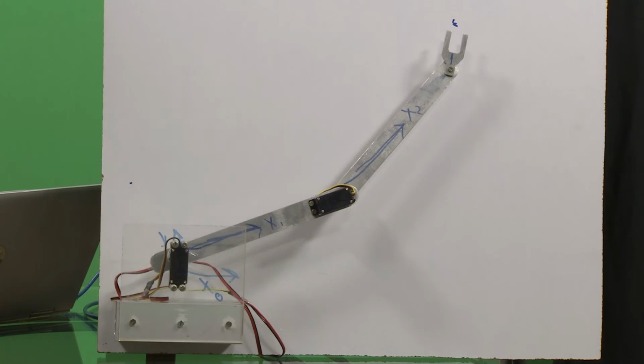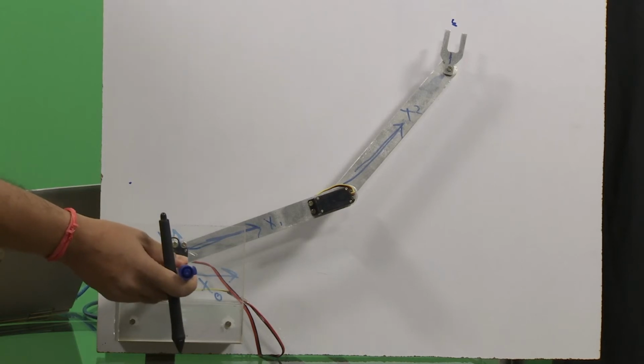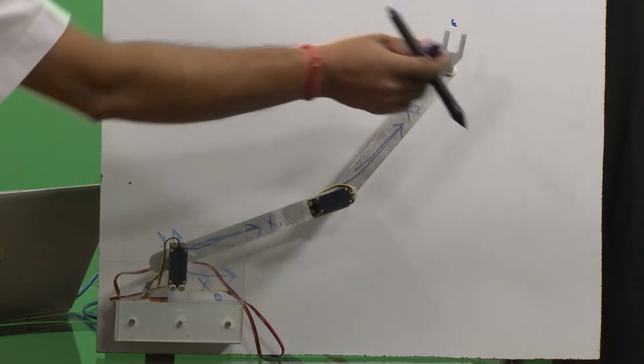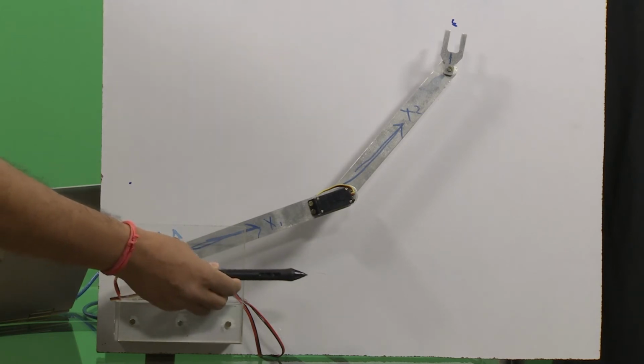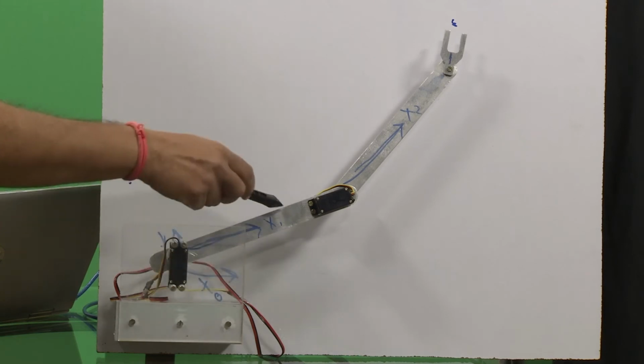Okay. So, DH tells us that we assign the z axis first about the axes of rotation or translation. So, z0, z1 are here, z2 is here and z3 is there. Next, it says the x axis is to be assigned. The first one, x0, can be assigned like this, which is the reference frame, it does not move. Then the next x is assigned along the link.